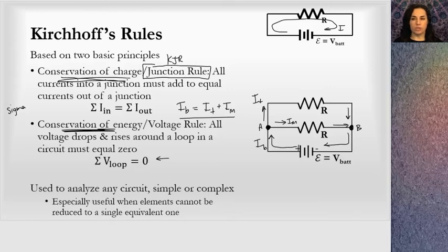And often that's what you're tested on, whether you can identify a correct loop in a circuit. So when I look at this circuit, there are several loops that I could do. The easiest one might be just to go around the outside. And notice that I closed the loop. It's a closed loop somehow. And I chose the direction of the current. That's the easiest way to do that.